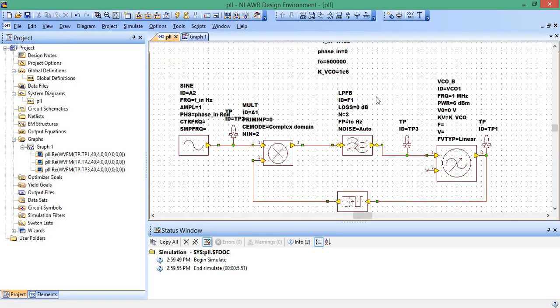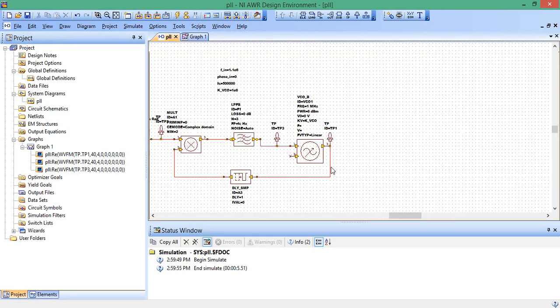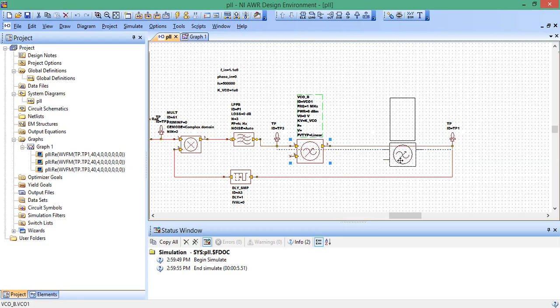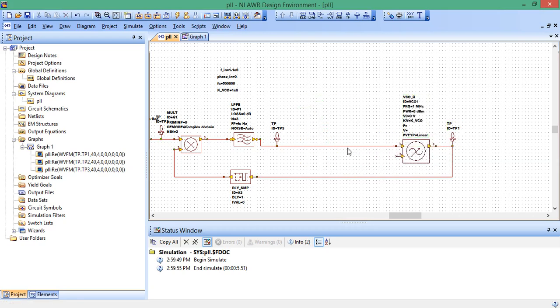Sometimes, in many cases, you want to lock not just frequency but phase. So how can you do that? What can we add to this thing to make it go from a type 1 phase lock loop to a type 2? We're going to add a PI controller. Capital P, capital I, if you want to look it up. A PI controller is used in control theory, and we're going to use it right here in our phase lock loop. It's basically going to model a charge pump, and it also models an integrator that you can construct with an op amp.